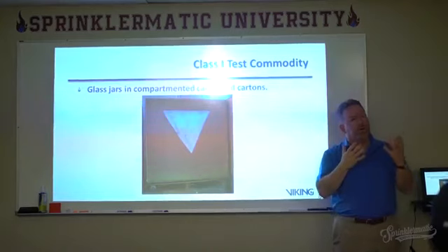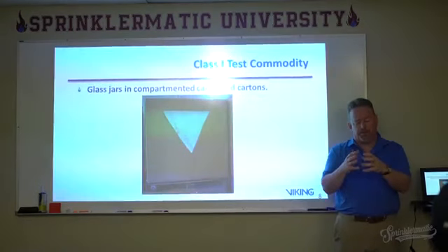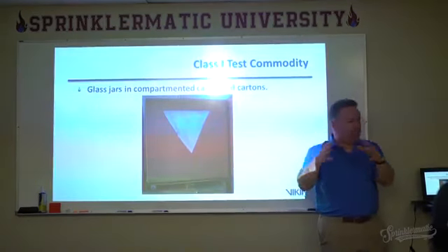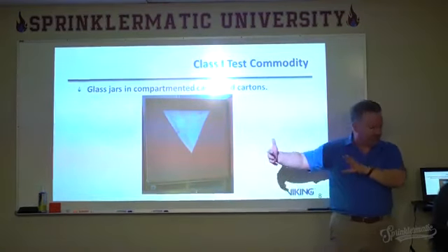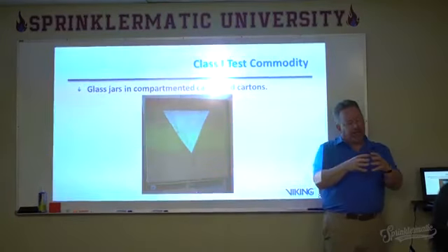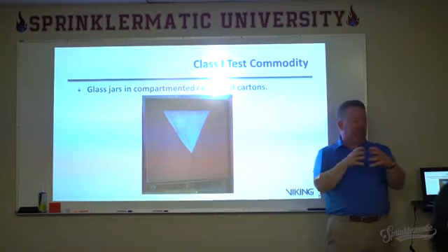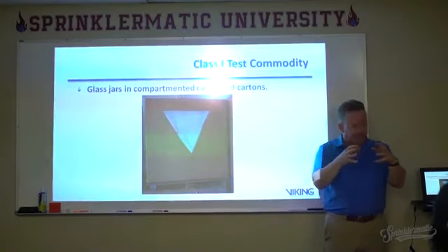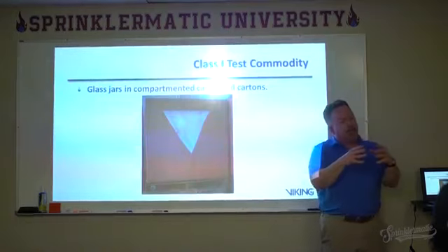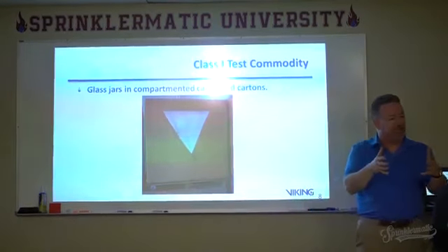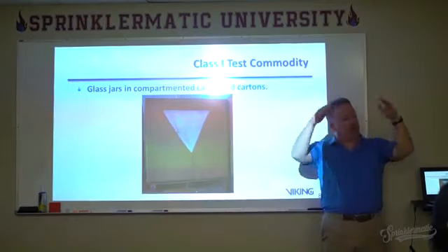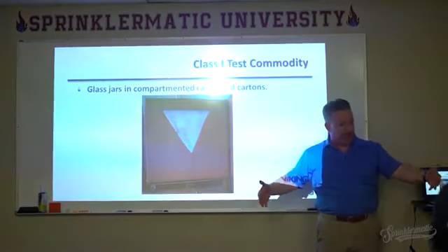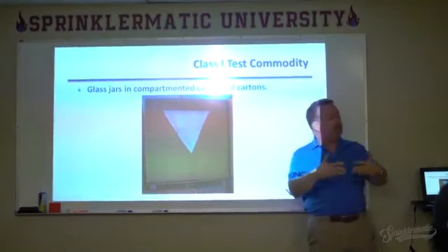What we have, in the sprinkler industry typically, is we convert this heat release rate. We look at how fast it burns, how much heat's coming off, and then we determine, through other tests, what we call its required delivered density. In other words, this commodity is going to burn at such a rate, it's going to require this much water to spray around it in order to control the fire.